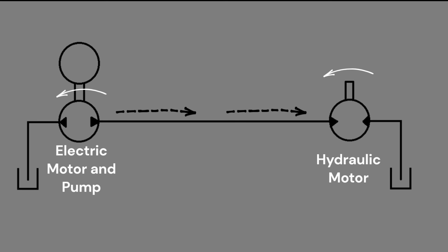This energy is no longer in the hydraulic system and results in a lower pressure after the motor. This pressure difference is commonly known as pressure drop. This pressure drop is required for a hydraulic system to do any kind of work.